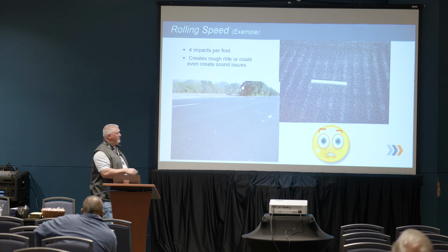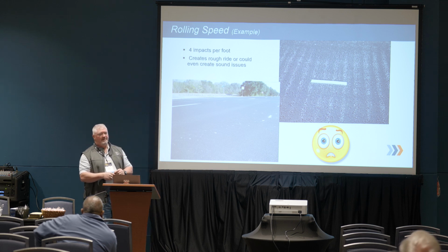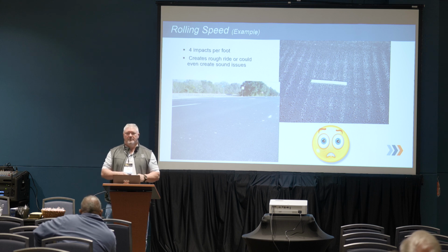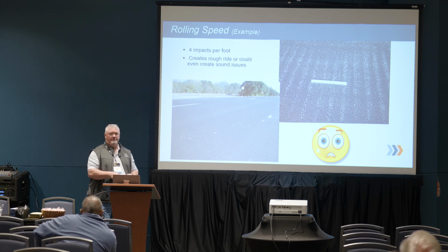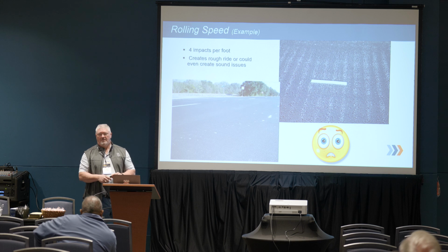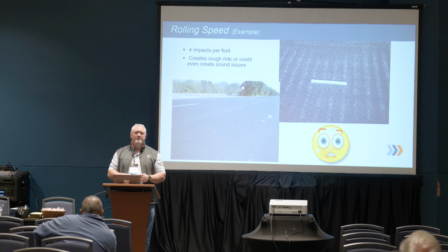Found out that the paving foreman was getting paid 50 cents for every ton. He was running mainline at 125 feet a minute. Now, if anybody knows anything about paving, you get over 65 feet a minute, you outrun your electronics. Might as well just take them off. But at 125 feet a minute, he would run out all his trucks and stop and wait for 45. Get the trucks back, run out 125 feet a minute, sit and wait again.